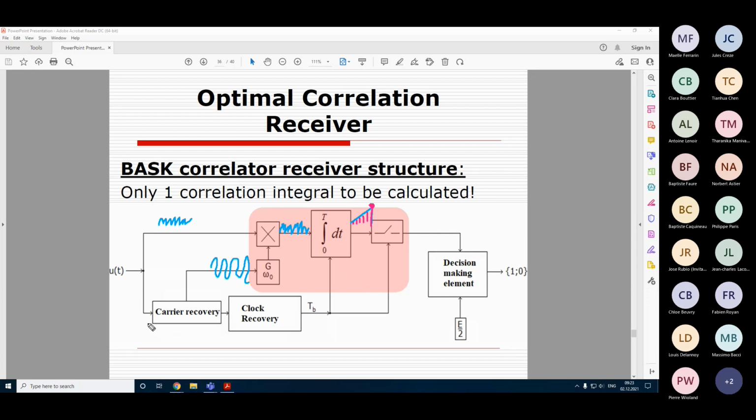In addition, of course, here comes all this synchronization, all these clock problems we were talking about. We need to have a carrier of the correct initial phase, so it should start with a specific 0, for example, here. For that reason, we need this circuit which recovers the carrier with correct initial phase and helps this generator to generate the correct carrier.